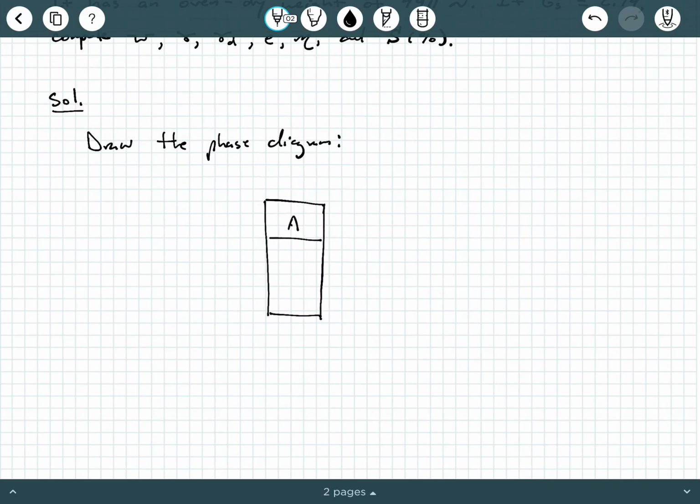Here we go. We have air, water, and soil solids, and I'm going to put the weight side on the left, with units of newtons, and on the right the volume side with cubic meters. On the weight side, the weight of air is negligible, so we have a weight of water and a weight of soil solids, and then the total weight.